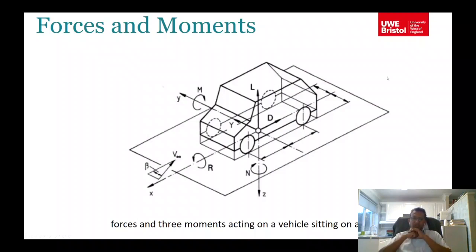Then you can look at the forces and moments on a car. That will be your rolling moment. That will be your pitching moment. That will be your yaw moment. That is your longitudinal force, that is your lateral force, that is your vertical force. So this is rolling, this is pitching, this is yawing.